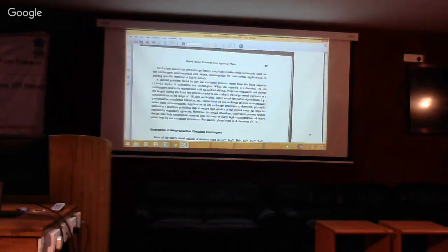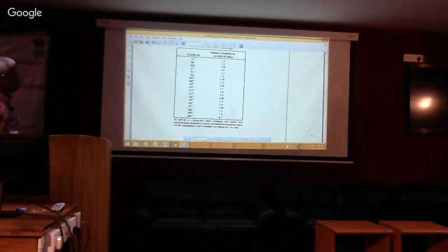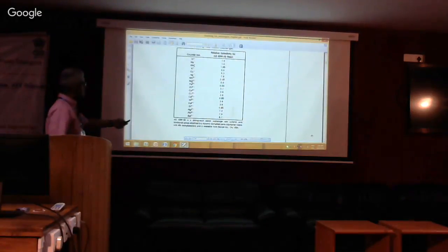And the second thing is, if you look at this resin, sulfonic acid functional group, how would you regenerate it? Well, you will say, okay, this is a strong acid cation exchanger. If at all I'm using it to remove nickel, let's say, I will put the resin in sodium form.